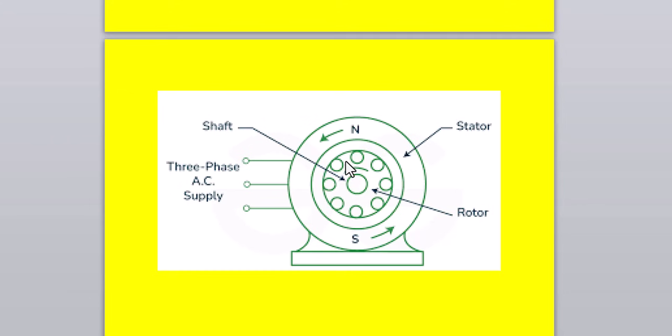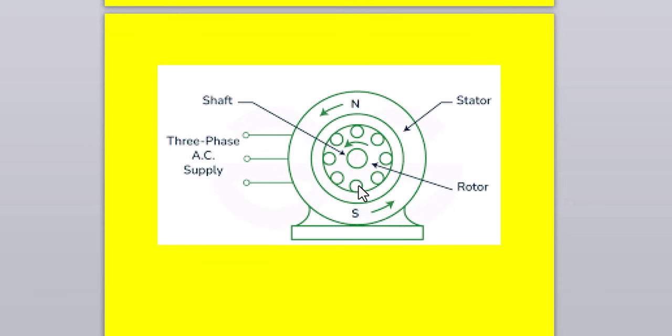The rotor is also made of laminations, that is core, so the core will also have core loss, but it is neglected because the rotor circuit frequency is very low. The rotor will also have friction and windage losses, and whatever is available on the shaft is called the total mechanical power output, that is called gross output. Before that, it's called mechanical output or mechanical power developed.